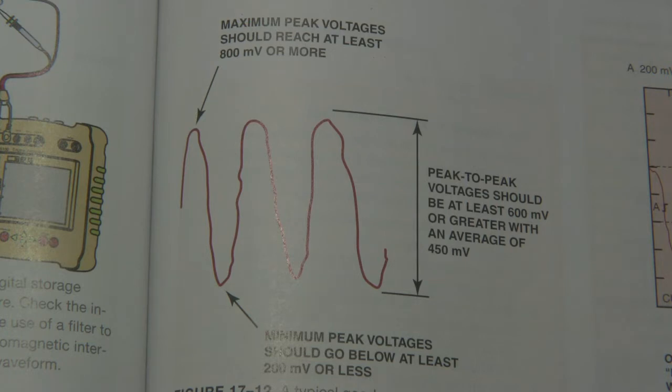And we typically see that happen on a cold oxygen sensor. It doesn't perform very well. And then as that oxygen sensor warms up, it starts to do its job a little better because oxygen sensors have to be up at an operating temp before they can work. That's part of the open loop versus closed loop scenario. We don't want to start monitoring fuel trims because until the engine's warmed up, we want to stay in open loop. We don't want to go into closed loop until the engine's warmed up because the oxygen sensor is not functioning properly until it's properly warmed up. Just like the cylinder heads have to be warmed up in order to have the fuel atomized correctly.